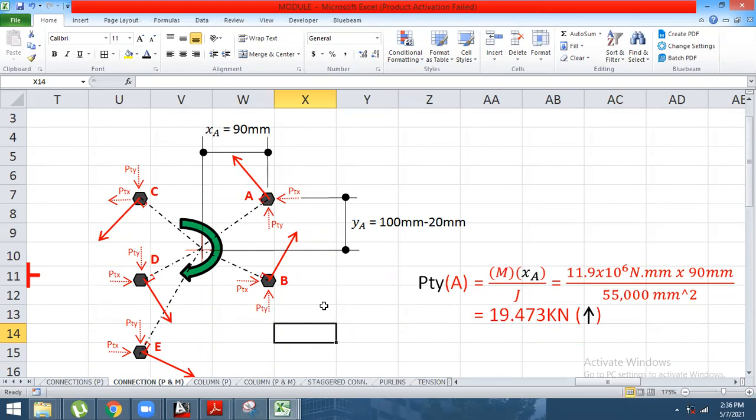Okay, ayan. Now, from that point, since there's a clockwise force, therefore the resistance would be counterclockwise. So those counterclockwise forces should be perpendicular to that distance. Okay, so therefore, this force is perpendicular. Then this force acting on C is also perpendicular. So as you can see, those red arrows can cause a moment which is counterclockwise. Yun yung ilalaban natin para dito sa moment na clockwise. Since force A is nakaturo siya ng paganyan, it is going in that direction.